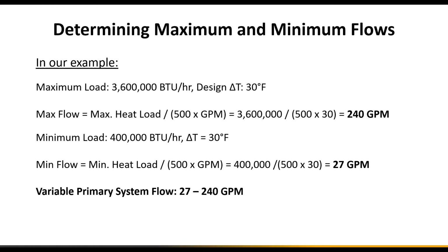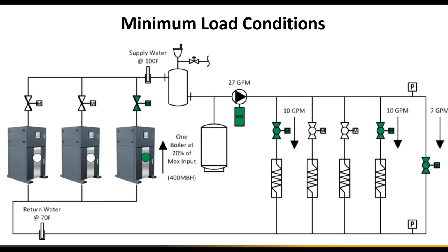If we then move on to the next slide, we can see here the 3 boiler units with a variable speed pump. We have a number of zones. At the far end, we see a pressure activated bypass. So if all the zones are maybe closed, then we simply have the variable speed pump drop into minimum speed and pump that water through the pressure activated bypass. As additional zones open up, the variable speed pump will ramp up because it sees less of a pressure drop.